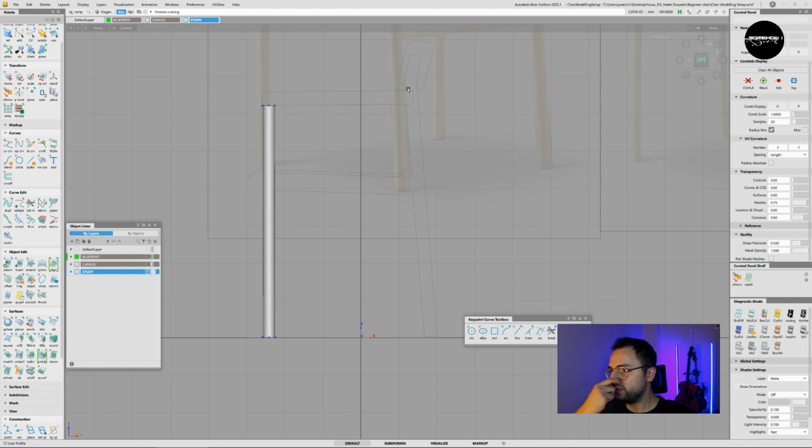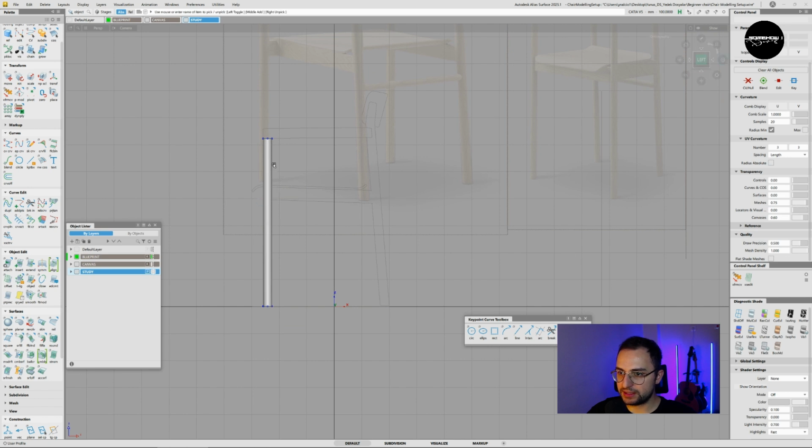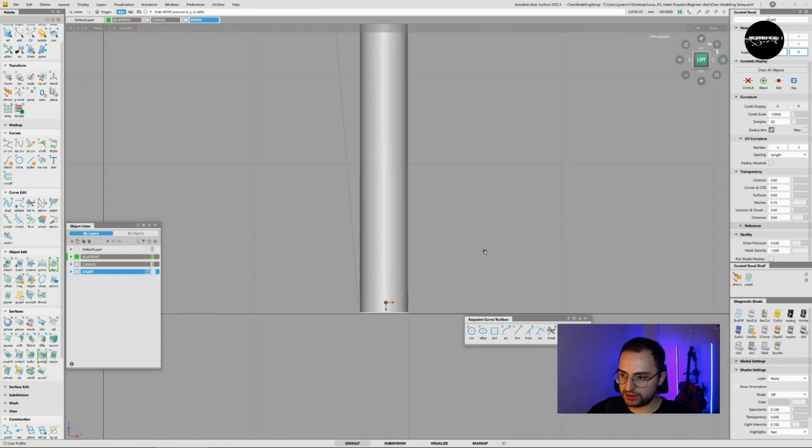We're gonna copy our cylinders for the other legs. Let's pick surface, Ctrl C, Ctrl V, copy and paste it, move, Ctrl Shift and middle mouse button, selecting move, slightly hovering on it and leaving it on the x-axis by middle mouse button since I am using orthographic view. Yeah, and my pivot point is here. So I wanna move my pivot point to the center of this surface.